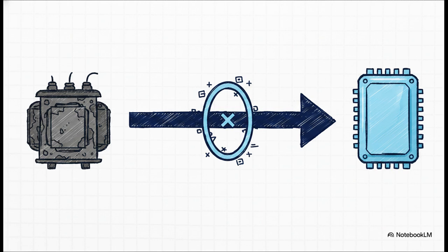Next, you update your impedance. Now, I know this formula looks a bit daunting at first glance, but it's really just proportional scaling. You are mathematically sliding your equipment's impedance over to your new unified grid standard. You scale the old per unit impedance by multiplying it by the squared ratio of your old and new base voltages and the ratio of your new and old base apparent power.